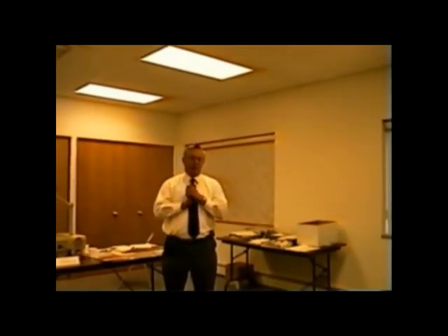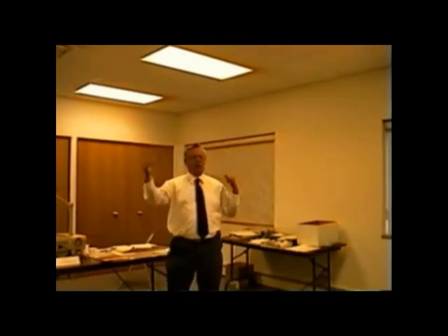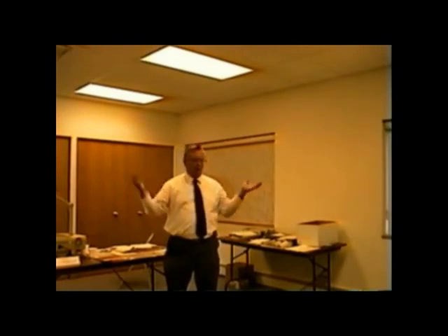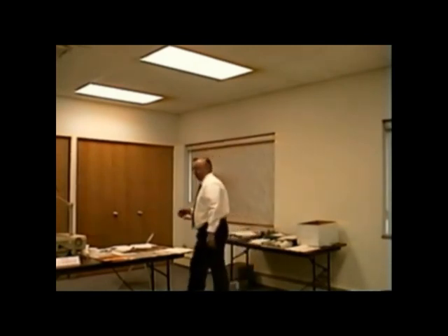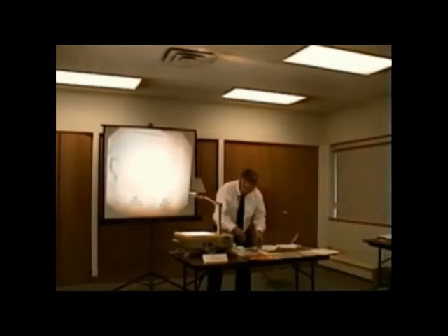All we're saying to you is that a major cause of technical problems is ductwork. I just can't tell you how many job sites we have gone on with brand new furnace installations, very luxurious mansion-type homes, multiple furnaces, all kinds of ductwork, and the ductwork is inadequate, furnaces overheat, heat exchangers crack, and so forth. This is the reason we have to be able to describe the ductwork. You may have to draw it out. You may have to fax it to us. We may have to discuss that. Okay? And in some cases, we may have to fax it to the manufacturer. But again, we've got to talk about ductwork. Okay? All right, so let's go back here to the overhead.